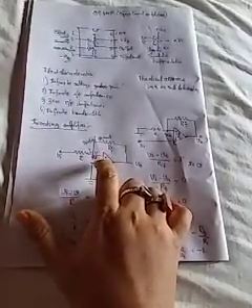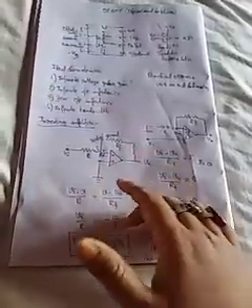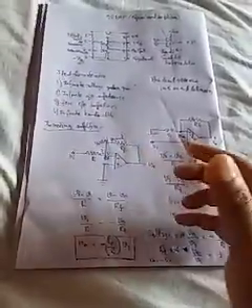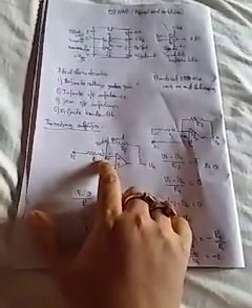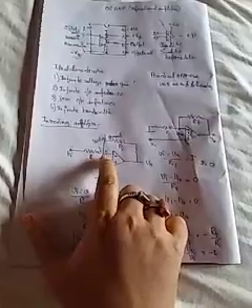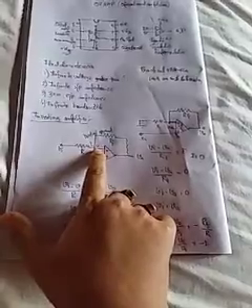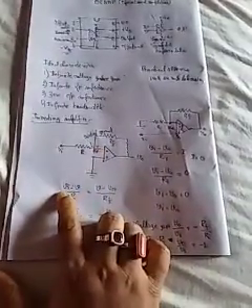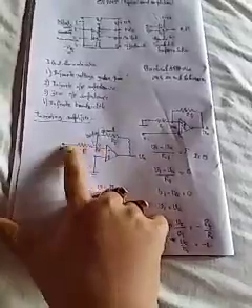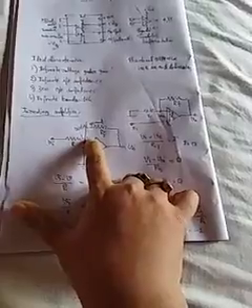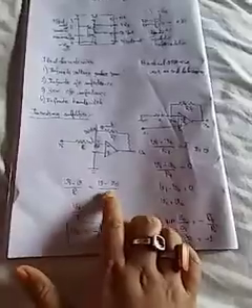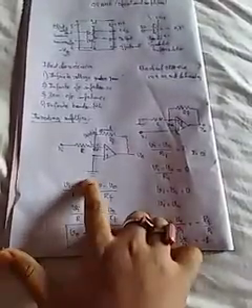But in the case of a ground terminal, whatever happens, ground can serve as a source of infinite current, but here it is not a source of infinite current. That's why it is called the virtual ground. If I consider the voltage here as V, then according to Kirchhoff's law, (Vi minus V) by R is equal to (V minus V0) by RF, because current is flowing through this terminal. But here V is 0, so it reduces.